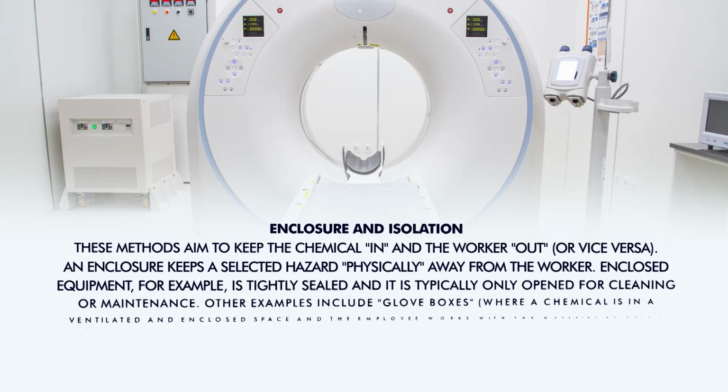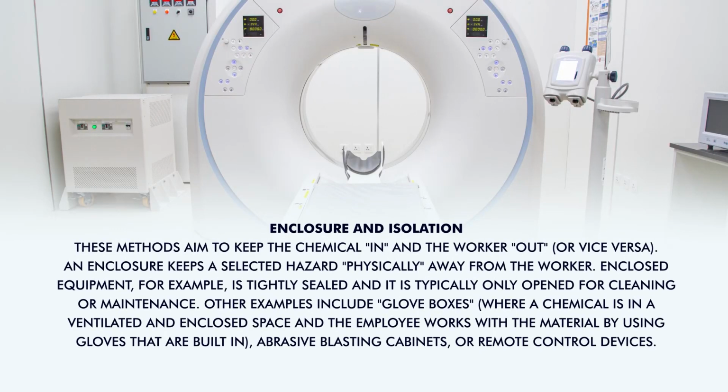So for everything we have to use a proper engineering control, and then execute it. For example, instead of conventional spraying, try to dip paint with a brush, or use airless spray painting methods. These are some of the examples I would like to give. Sometimes you can use automation, which means fewer workers have to handle or use the materials. And enclosures as well as isolation are also important methods for the management.